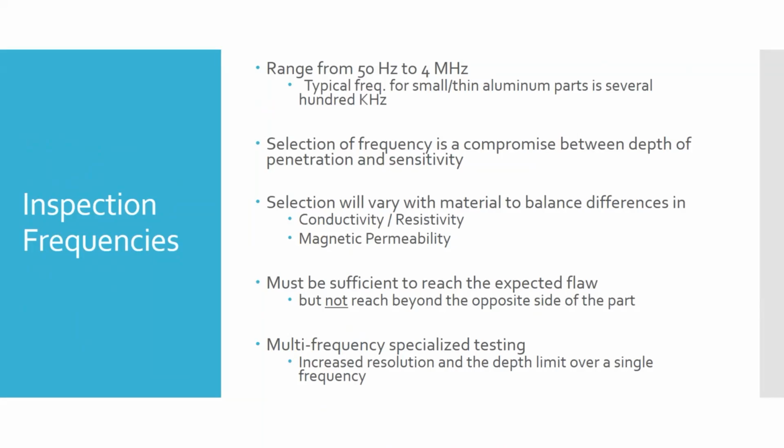Some probes lend themselves more to high frequency, some to low. And then some of these really sophisticated ones might have more than one coil in the probe, where it can do a high frequency, low frequency, high frequency. So you can get that high sensitivity at the surface, and lower sensitivity but deeper penetration with the low frequency. So put that all together. I'm going to leave off there.